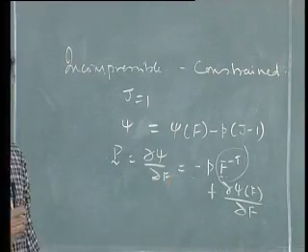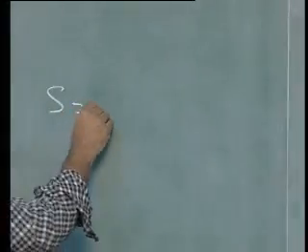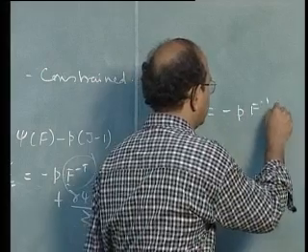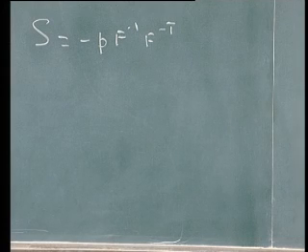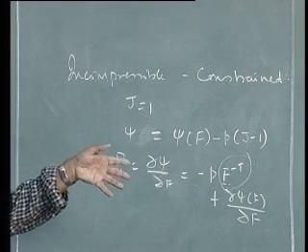S is equal to minus P F inverse transpose. That's the relationship. In this case it becomes S is equal to F inverse P.